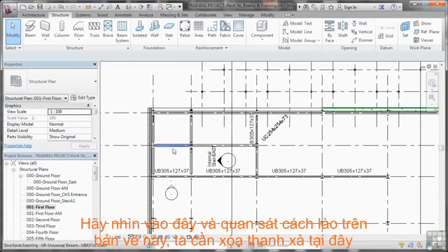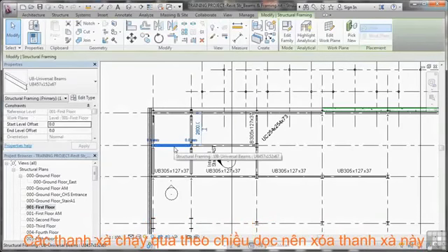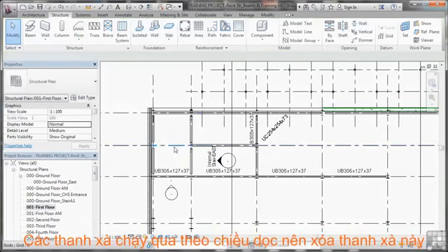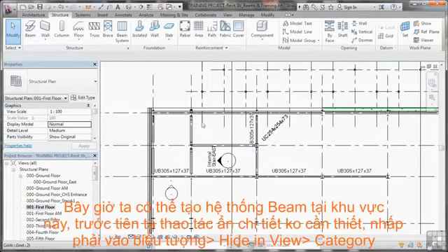What exactly have we got in place here in the first floor? Well, the first thing we have here is we have a stairwell. So there wouldn't actually be a beam there. It would actually clash with the staircase that's coming up through that vertical penetration in the building. So let's delete that one there. Okay, here though, you might have a beam framing system.